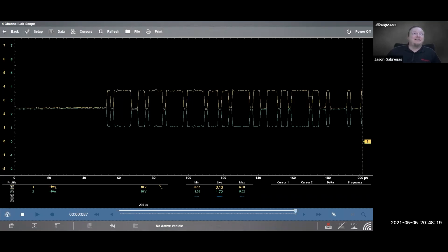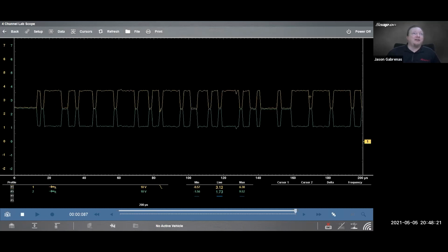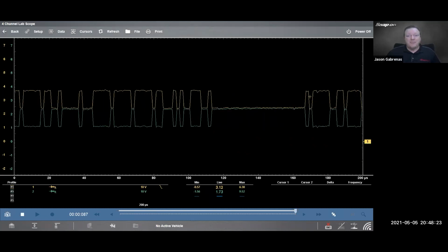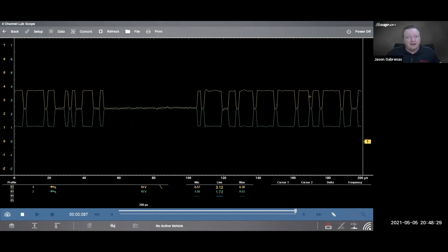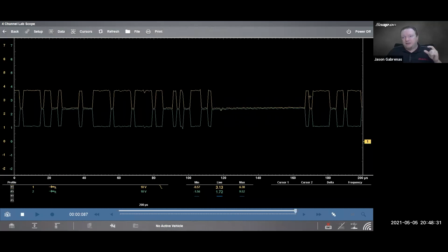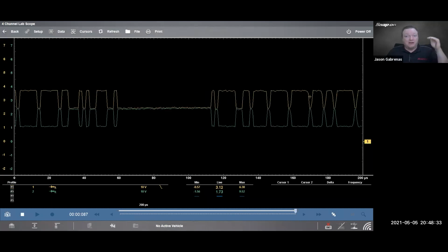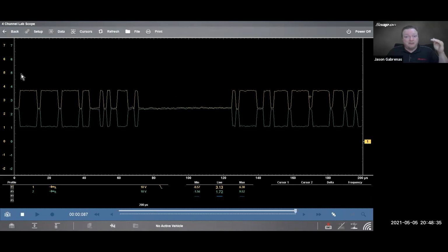So let's see, Luis says, is the circuit always running on the 5-volt circuit? Well, we got 2.5 volts on both sides. So it's really that differential. It doesn't quite get all the way to that 5 volts, and that's a good thing, right? If it's shorted to 5 volts, that's an anomaly. That's too high. That's up here, right?